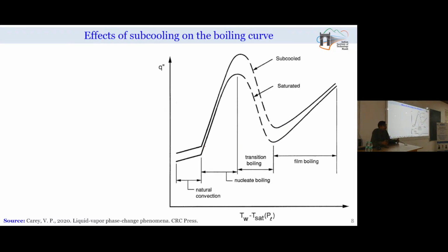Another important parameter is, though we say that whenever we are operating under pool boiling conditions we have to keep the bulk liquid at saturation temperature, the majority of the time we are not using any secondary heater for heating our pool. If we only use the heater from which we want to study the boiling to heat the entire pool, then the liquid close to this bottom heated surface will be at saturated conditions, but further away we may have bulk liquid at subcooled conditions.